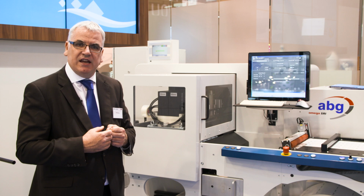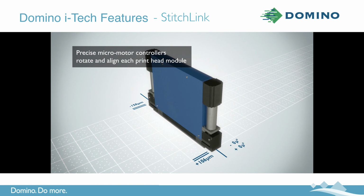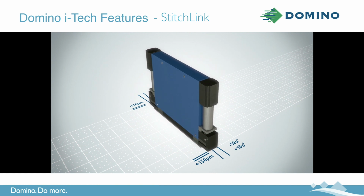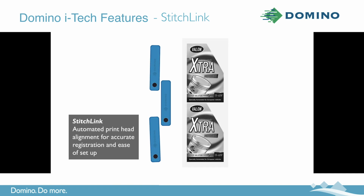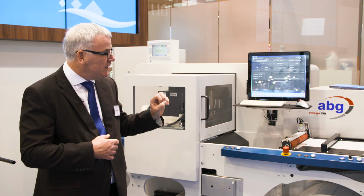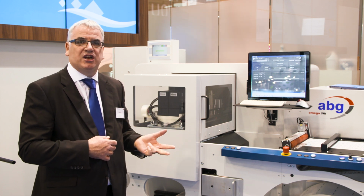Finally, we have Stitch Link. Stitch Link is our micromotor controller system that enables us to align the three modules or the multiple modules depending on the part width we have within the K600i, because if they're not aligned then we'll tend to get white lines formed between the modules. So it's a highly precise process, so we can align those modules in two different axes to give optimum print quality, less operator involvement, and reduced risk of product rejects. So, intelligent technology from Domino: Clean Cap, Active Flow, and Stitch Link.